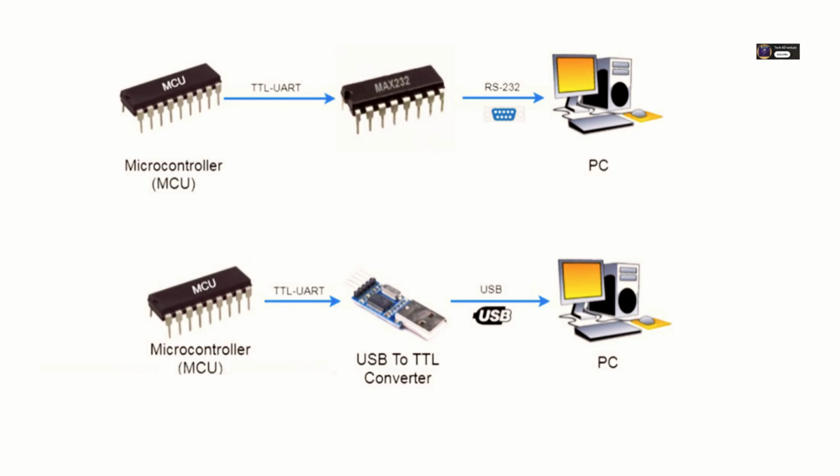What about distance? We talked about protocols like RS-485 for long runs. How far can standard TTL UART typically go? Standard TTL UART, the kind directly from microcontroller pins, is really meant for short distances. Think connecting chips on the same circuit board, or maybe across a cable of perhaps 1 to 2 meters maximum under ideal conditions. If you need more distance, RS-232 can typically manage up to around 15 meters, maybe a bit more, depending on the baud rate and cable quality.